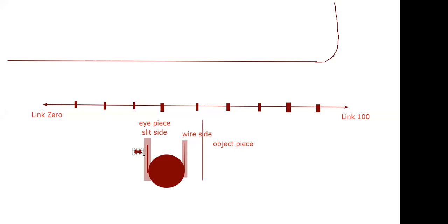Okay, this is the eye, the wire, and this is the ranging rod. If these are on a straight line, this will be done like that. Okay, you are standing at link 10. You have asked your friend to place the ranging rod somewhere along this corridor edge, either the edge of a road or a wall. You looked through this slit yourself and aligned the ranging rod exactly behind the wire.